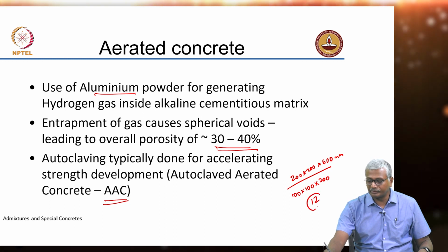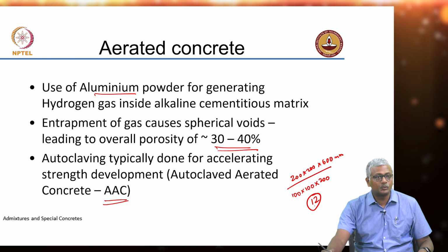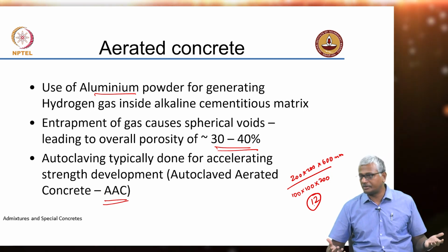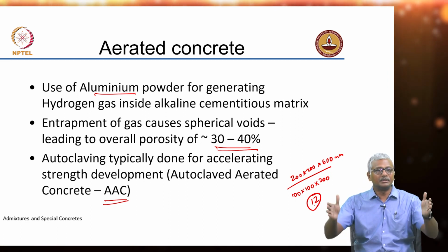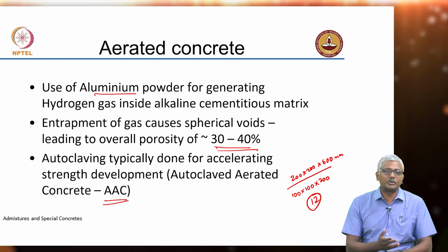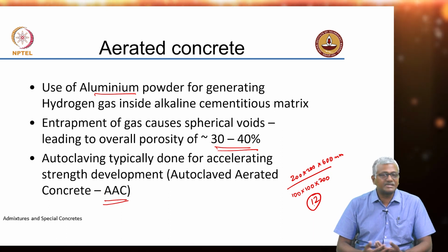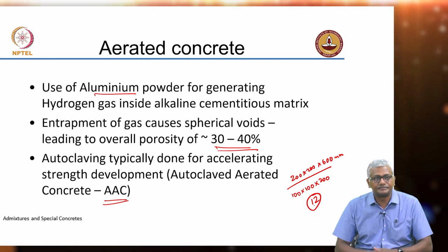So, 12 bricks, the volume of 12 bricks comes in one block, and this block is fairly light in weight because of the lightweight concrete nature. So, you can actually have one worker put this in place. There is a single mortar joint, right. So, it increases productivity significantly. Instead of lifting 12 bricks, now you are lifting 1 block, right.